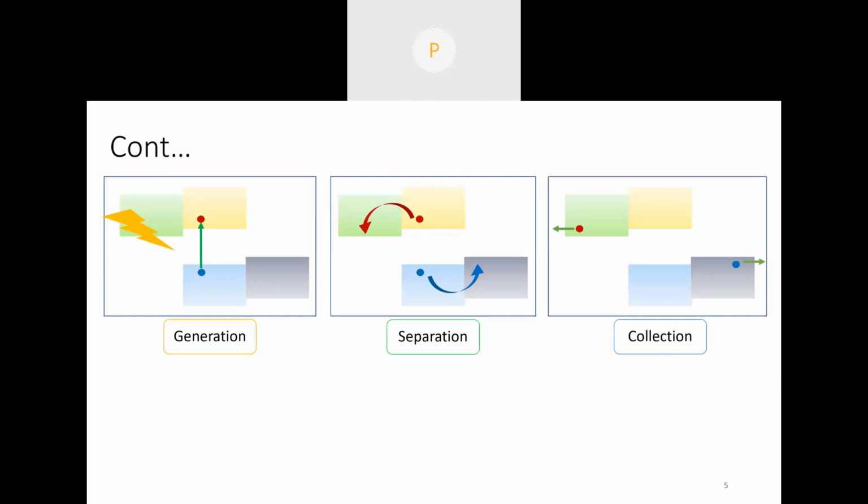But for solar cell application, we need to separate these charge carriers. We don't want them to recombine, because if they recombine, then it will not be a solar cell. It will be like a LED. So we have to stop this recombination. We have to separate them. For that purpose, we apply extra layers, called the electron transporting layer and the hole transporting layer. So electron transporting layers are selected in such a way that their conduction band is lower than the conduction band of your absorber material, so that your electron can easily move towards that side.